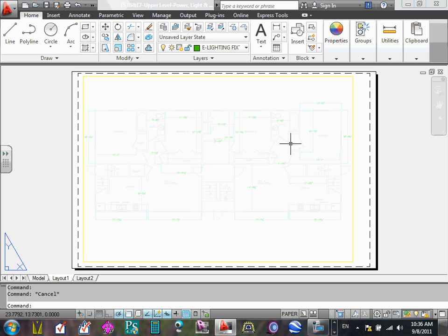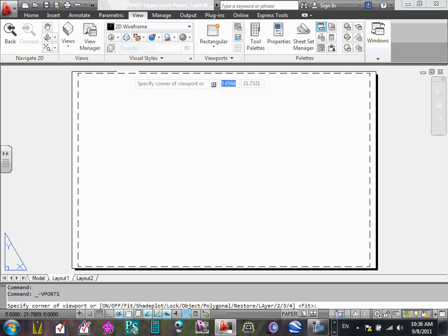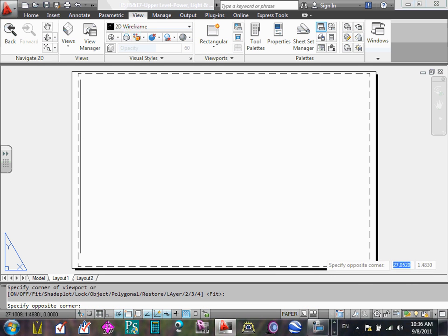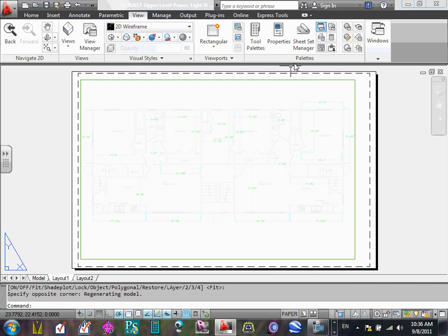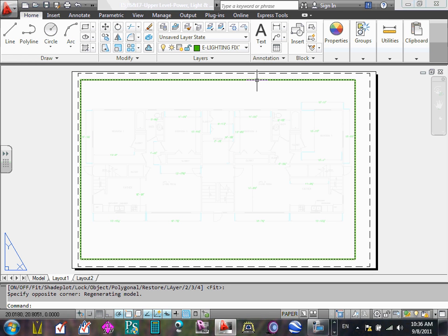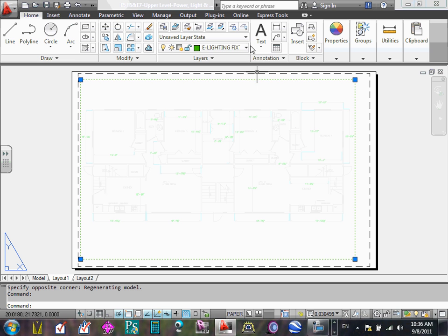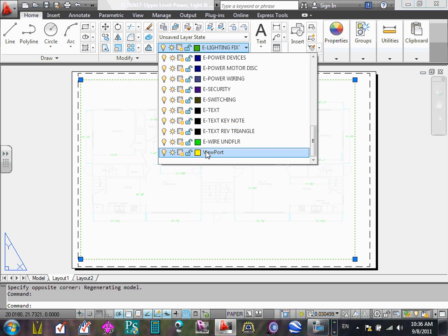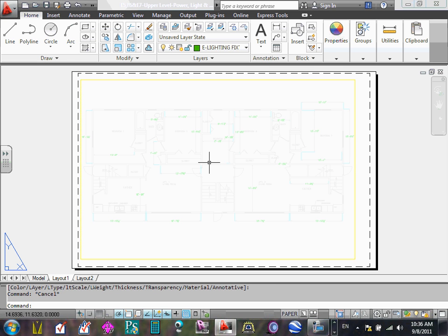One more time, let me delete it and bring it. So click, delete, view, viewport rectangle. Click on one corner. You can make it as big as you want it to, except I made it on the wrong layer again. So what do you do? You go to home, pick it up. See, Chris picked it up and went to the right layer and put it on the right layer, which is viewport layer, and escape. Any question, guys? Any question about the viewport? As a lot of you who are working with CAD know, you can bring as many viewports as you want.